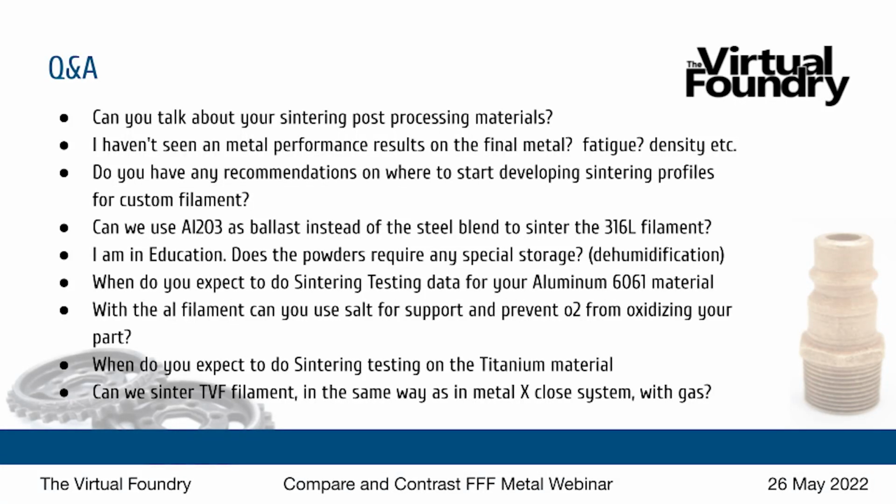Brad, can you use salt for support and to prevent oxygen from oxidizing your part during debind and sinter? Yes. And in fact, table salt has a melting point, I can't remember what it is, but it's around 1400 F. I've actually done sintering in a molten salt bath, which was a very interesting and kind of terrifying experiment. But I had success. If I had more time in the day, I would go back and spend more time working with that experiment.